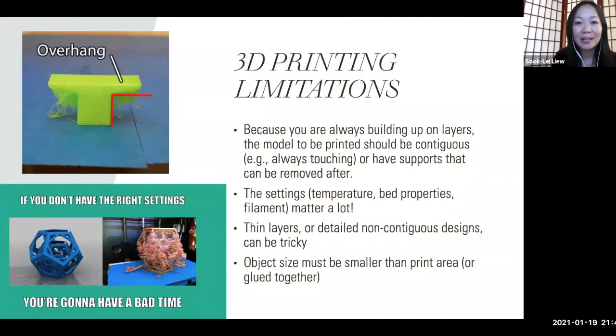They tend to be like boxes, like solid objects. Even things like this you can print actually, but the design, in this case, if this is what you wanted in the end, you should just flip it upside down so it prints the solid top part first, and then it can print this on top of that because that will make for a much better print design in the end. And then when it's done, you take it and just flip it back the other way.